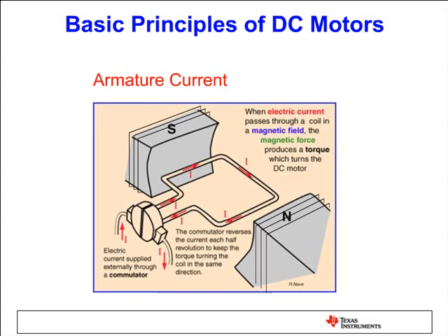That's another feature of the DC motor, and it's very important again because, as I will explain later, this will help us to maximize the torque generation. In an actual DC motor, we have several conductors like this, maybe tens, hundreds of conductors, and only the horizontal ones, which are aligned to the brushes, conduct the current.